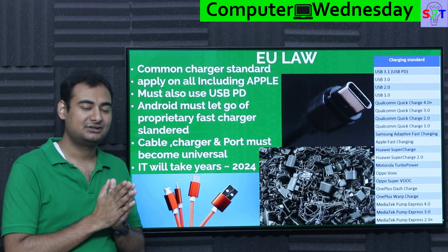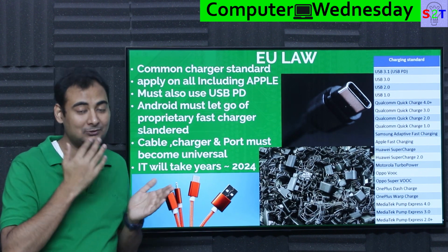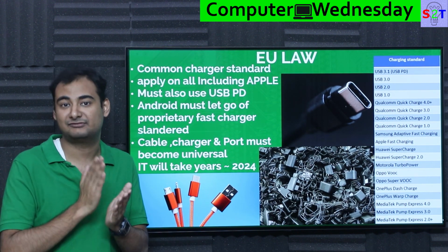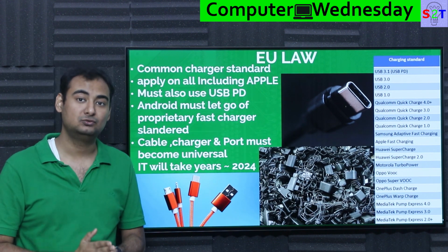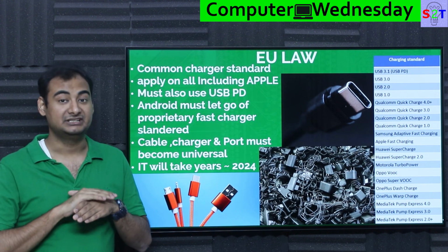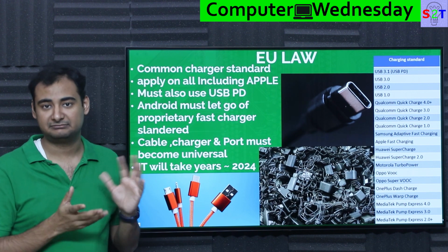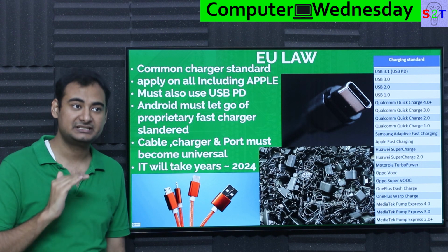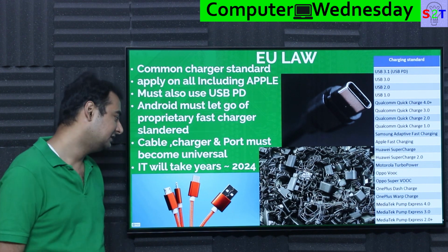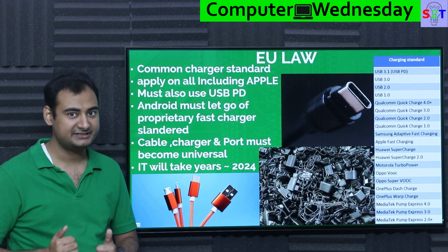It's like Android found the same kind of loophole. The loophole was that it must support USB standard for charging, and they did that. Every Android phone can accept 5 volt 2 amps, basically 10 watt charging without any issue. And if there is any hint, like fail in handshake, it will default to 1 amp connection. So basically your phone will be charged on any charger. That's the whole point. That's the amazing aspect of it.